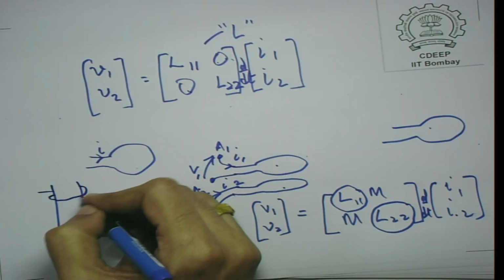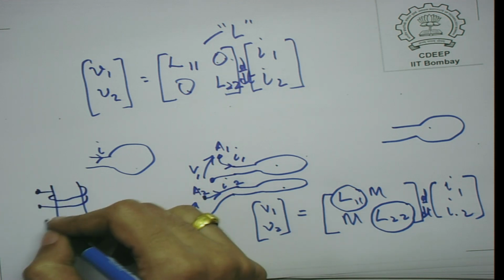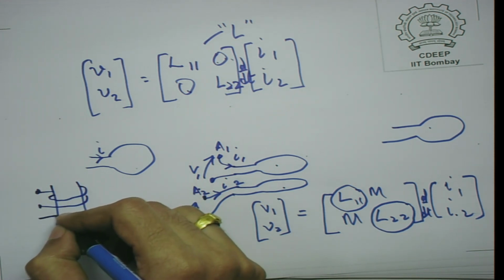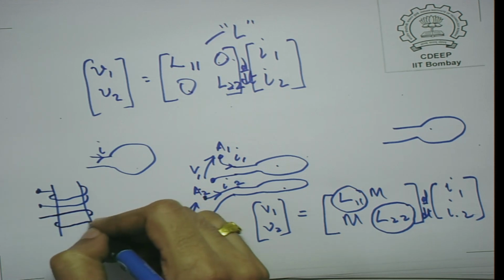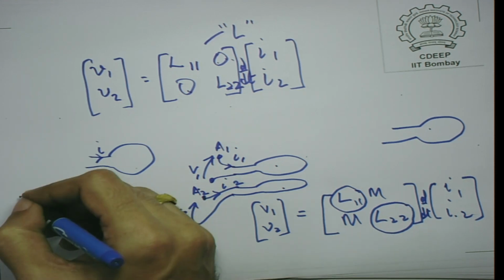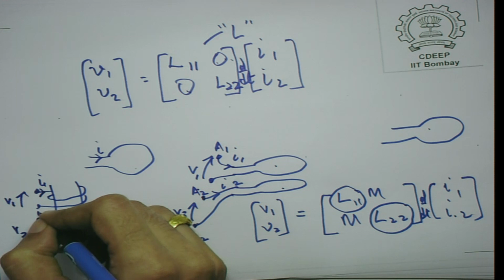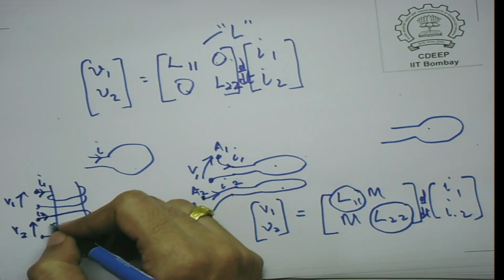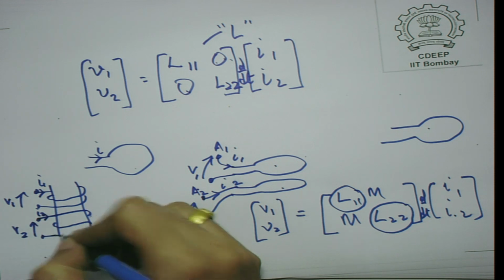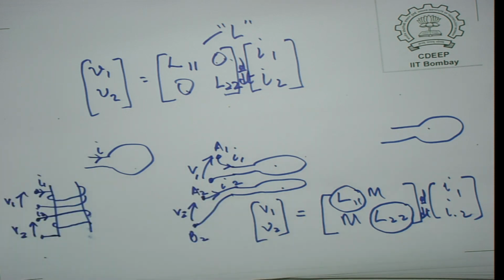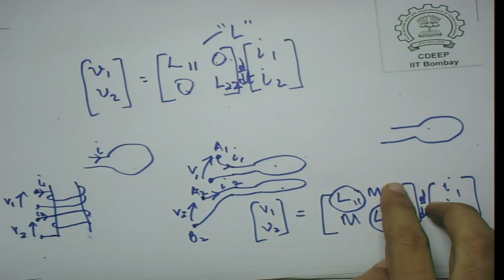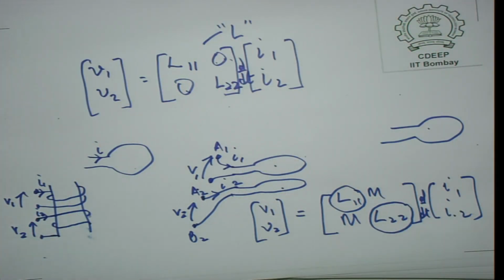the coils. So, if you have one coil wound in this fashion and another coil wound in this fashion, and you are measuring V1, V2, I1 and I2, this voltage is measured this way. In that case, you will in fact find that the mutual inductance comes out to be negative. One point which I mentioned some time back was that in the mutual inductance matrix here, the off diagonal terms are equal.